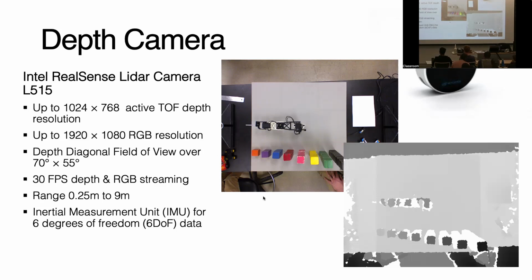It has a solid state LiDAR in it that scans the environment using a time of flight sensor and gives you readings of how far away pixels are from the camera. In the older stereo camera style, the Kinect worked by measuring the distortion of a fixed IR pattern it projected on the world, and then figured out what the depth was to the pixels.